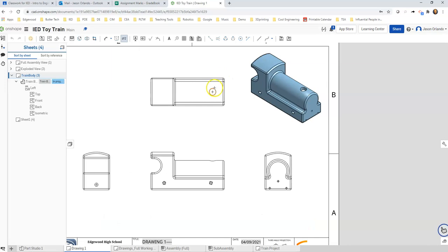And clicking on a hole and pulling away works as long as you had used the hole tool. Now, if you had made a sketch and sketched a circle and then done an extrude remove, the details of a hole, like a diameter and depth, are not both going to be stored there, or threads, etc. But if you did start a sketch with a single point and then use the hole tool to define the diameter and depth of the hole, that information is already stored there.